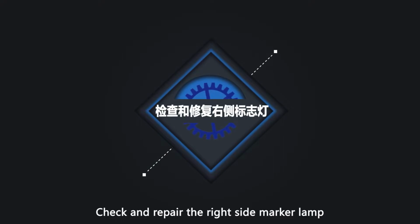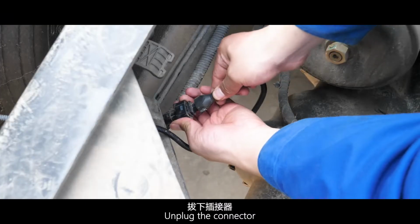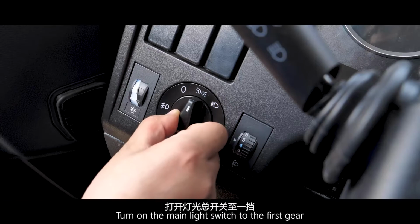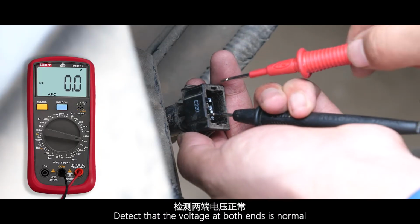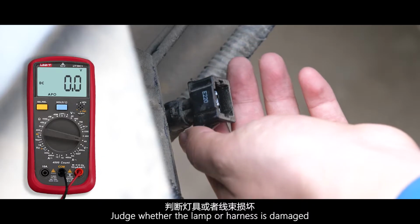Check and repair the right side marker lamp. Right side marker lamp and its line position. Unplug the connector. Turn on the main light switch to the first gear. Detect that the voltage at both ends is normal. Judge whether the lamp or harness is damaged.